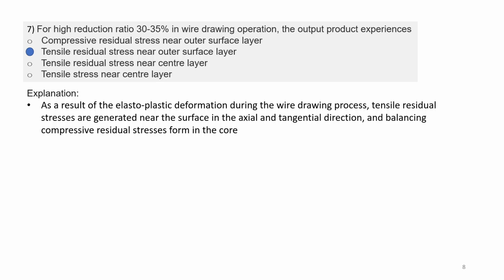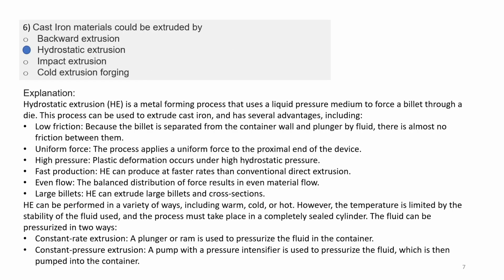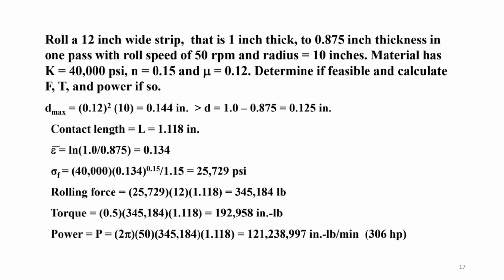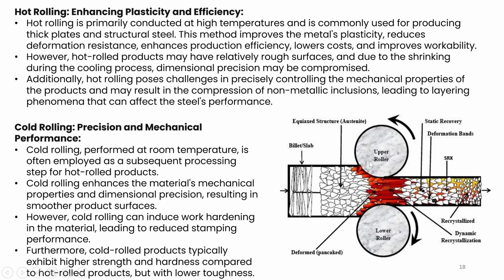So as in extrusion as well, it will be similar to this, but this will be a die opening rather than rollers. In this part as well, you can see the more material will be squeezed and where should be the compressive part. So in the center line, in case of wire drawing, you will be having compressive stresses, and at the outer part there will be tensile stresses.